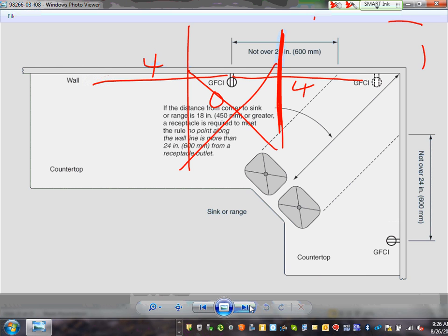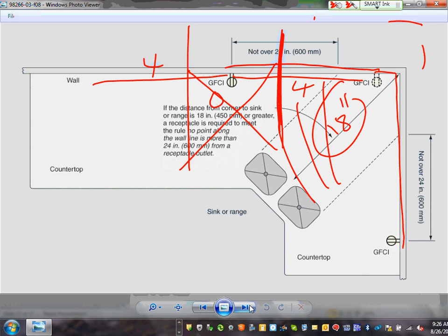So same thing, I think there's another one. How about kitty corner? If it's set up kitty corner, 18 inches or more, then it will count. Can you guys see how we count them? So this area here, would it count? Or should I start my measurement from here and here? Well, what's going to decide is how far is the setback. Is it 18 inches or more? Yup. Less than 18 inches? No. Any comments, guys? So we're getting into the details.